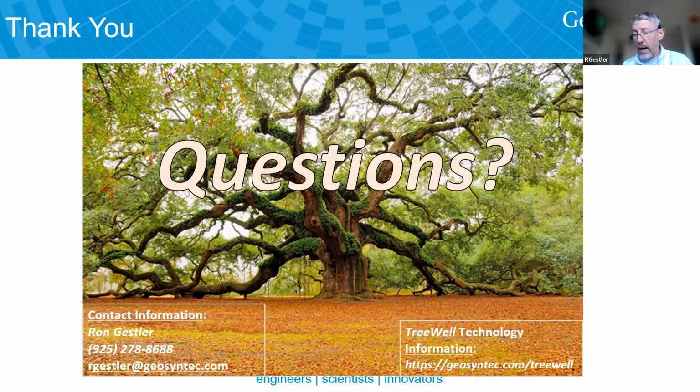That's why we've got those eucalypts. That one site that I presented. Now they're not conifers, but they're evergreen plants, evergreen trees. So year-round transpiration. That's a big benefit if you desire to see hydraulic control, right? We're never going to lose hydraulic control if we design the system properly and use evergreens. I've worked on projects where we needed to take out the eucs because they had too much influence on some nearby creeks.